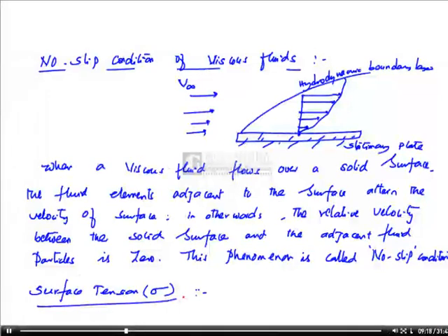On the other hand, the force of attraction between unlike molecules, like between the molecules of different liquids or between the molecules of a liquid and those of a solid body or container, when they are in contact with each other, is known as force of adhesion. This adhesive force enables a fluid or a liquid to adhere to a solid body or a surface. In fact, surface tension is due to the intermolecular cohesive force.